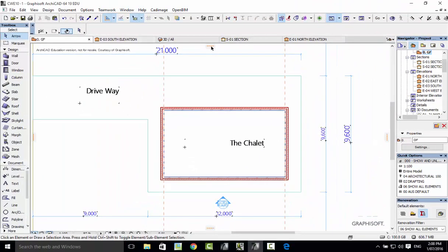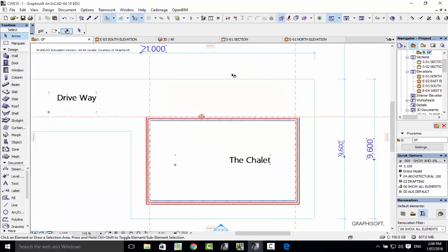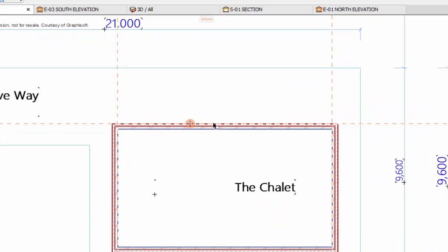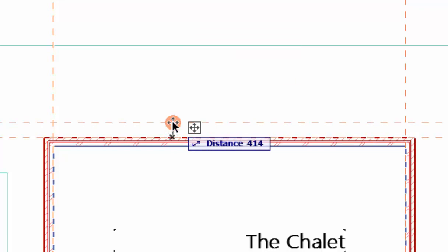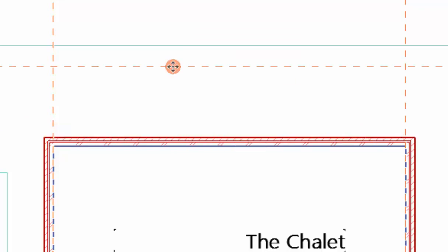And we're going to connect a guideline to the outside of our perimeter wall. Now we're going to move those. The curved wall is 2 meters away from this wall, so just grab the cursor, the orange cursor, drag up. As you drag, just type in 2 meters, and there's our position for our wall. It's got to go in.